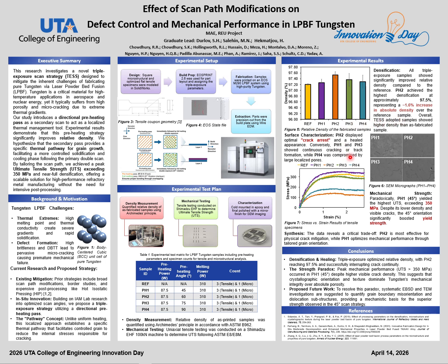Then I want to talk about the AFM images. AFM images reveal a clear sensitivity to scan orientation. In PH2, as we can see, we have a healed microstructure, what we expected, while crack continuity was successfully arrested. That's why I see a very smooth surface here. Conversely, PH3 shows reappeared crack tracks, and in PH4, we can see the same kind of continuous cracks with additional defects on it. So we can expect that these are very directionally dependent results.